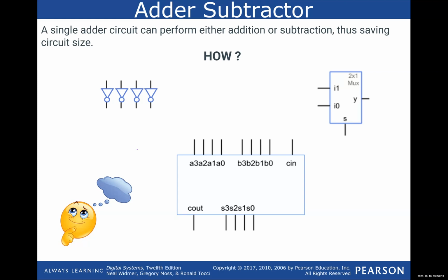So, I drew boxes to show they're all multiplexers, but that first one we connect to those and have the straight input and the complement of it. It goes down and each of the multiplexers would have the same one selecting. Okay, so you're doing it for the A and the B? Because I can give you either one negative. No, it's always going to be A plus B, A minus B. Okay, so the only one that would change is B. So that side would be the same where they're all getting selected by that first one. Because if it's one, it's going to switch it to the negative.